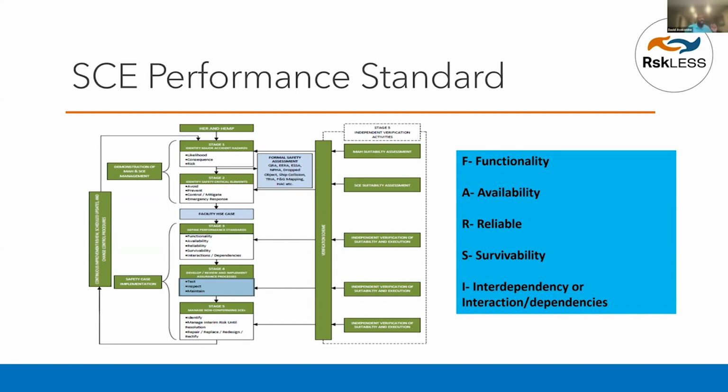The next thing you want to do is find out: is your SCE available? And that's why if you look at SIS or Safety Instrumented Function, they do a proof test to be able to check whether it can perform when demand is placed on it. Is it available when you need it? Is the PSV available when you need it? Reliable. Will it take me to a safe place?